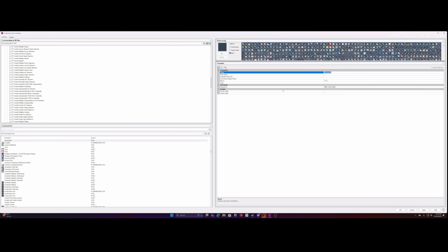Yes, hit enter and let it run. And then I would sit here and run purge and select what I want it to clean up, and then hit enter. It'll ask me to verify names. I would say no, and then it'll go ahead and do that, and then I would run another command like overkill, right? A lot of command inputs, but what if I could string them all together to make one button that cleans everything, right?